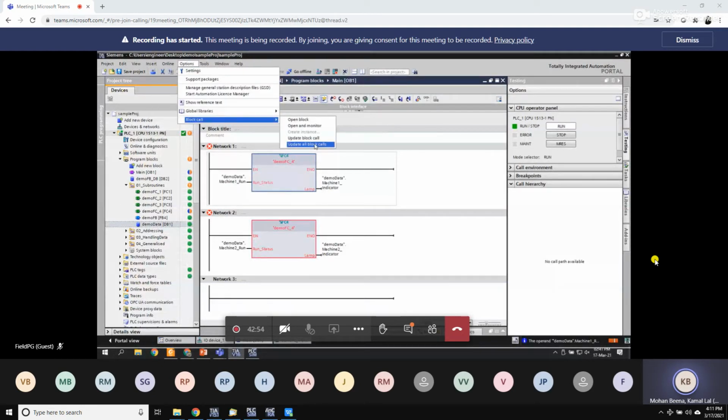Now here I have already prepared one timer before, that was timer 1. So I'll give timer 1. I'll make sure that the second time I don't give the same timer 1, I'll pass a different timer in this case. But how to create a DB for the timer?